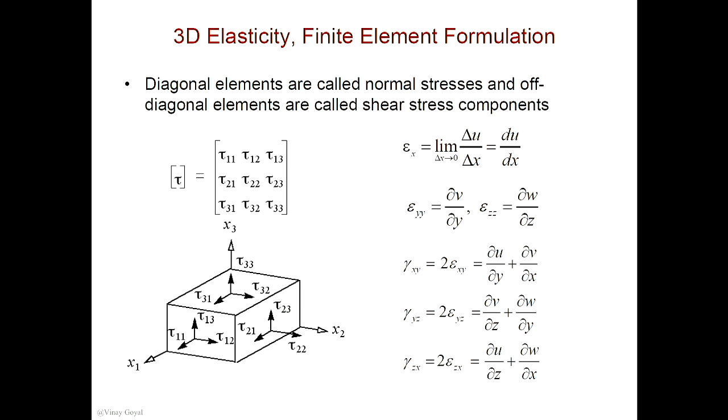You also have the strain field. These strains are a function of displacements, and these strains right here are the normal strains, and these normal strains also act to expand the cube, while the shear strains act to distort the cube, and so they actually represent the change in angle. This is the displacement field. We covered this in lecture number 4. Please go back and re-review. This is a summary of that lecture.